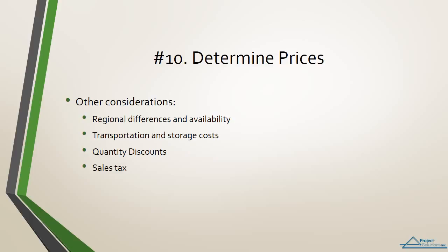As far as how to actually consider the factors, you need to be aware of the site conditions, another important reason for the site visit. You need to contact your suppliers, and your company needs some experience performing that type of work. Many vendors will provide discounts for large orders, thus enabling you to lower your estimate. However, you must obtain this information directly from the supplier, not from cost books. As consumers, we are all familiar with sales taxes. Be sure to take possible sales taxes into account for construction purposes as well.